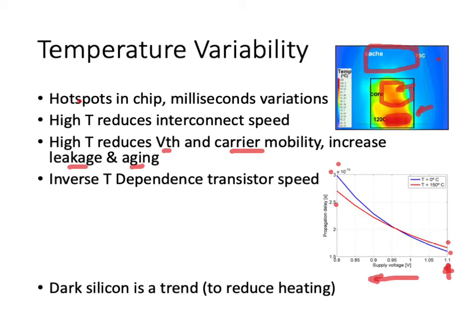a lower temperature. Let's try to explain this inverse temperature dependence, because there seems to be a sweet spot of supply voltage where the behavior of high or low temperature inversely changes the speed relationship. Let's first consider the case of a high supply voltage.